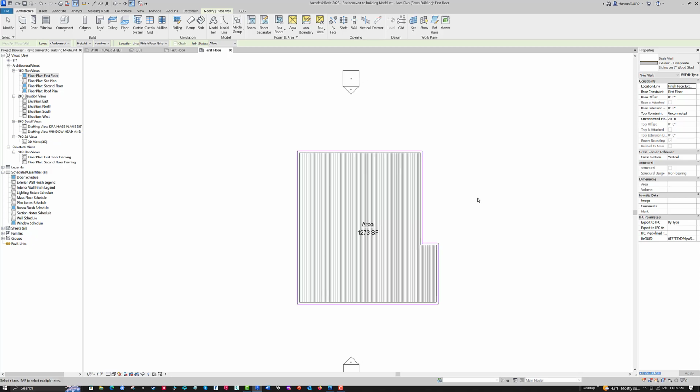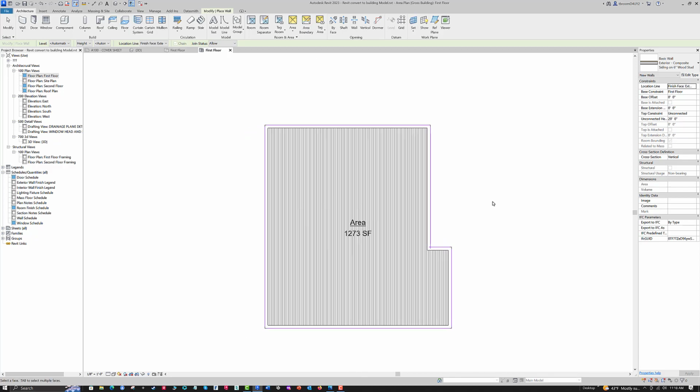It's too small though. I need it to be 1304 square feet. So I think what I'll do is go back to my first floor plan. Well, I can do that in this floor plan. I don't need to change. What I need to do is decide how to make it bigger. Now, I don't want to change the width of it. I've got that based on the site and the setback lines, and I really don't want to change this. So my only choice here is to really move this wall here back a little bit.